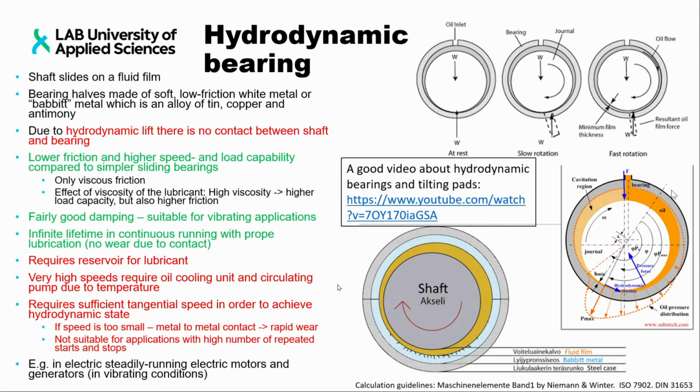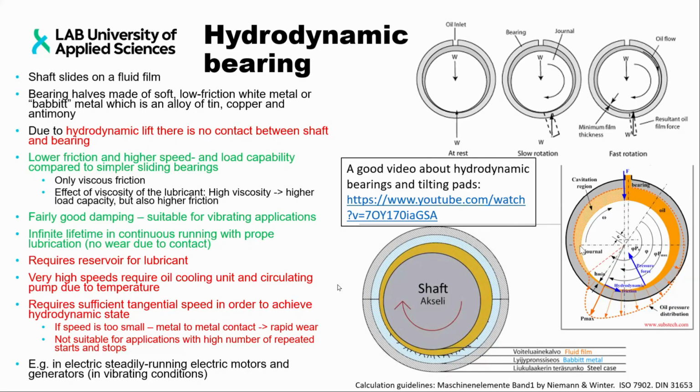It also provides information about tilting pads, which is a special design of hydrodynamic bearing, where the bearing is formed in different sections which can independently align themselves. One of the downsides of the basic function of a hydrodynamic bearing is that you need to have quite a precise form of the cavity between the shaft and the bearing.